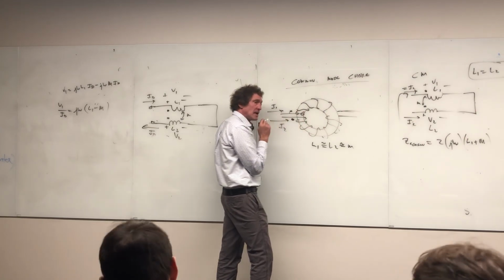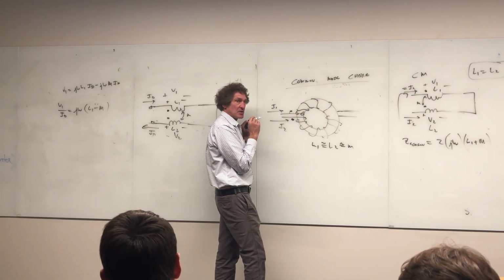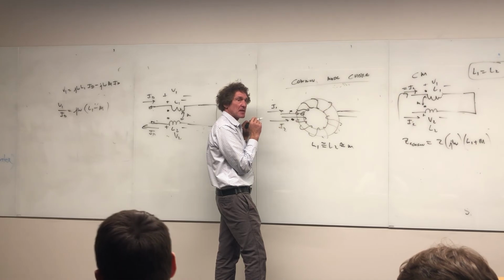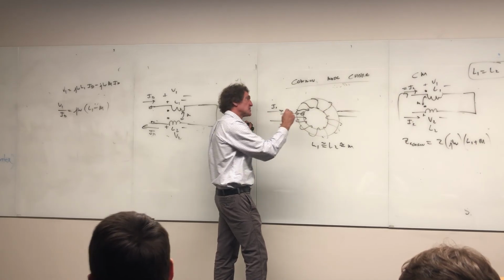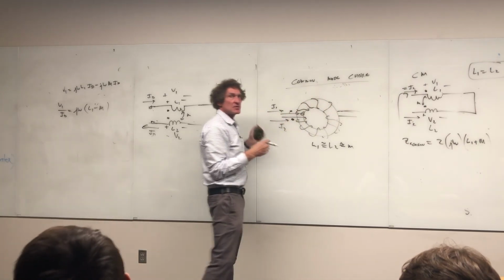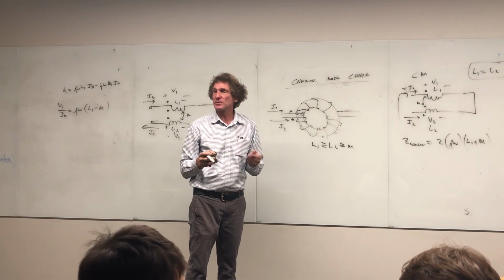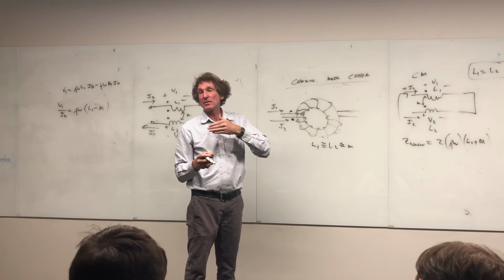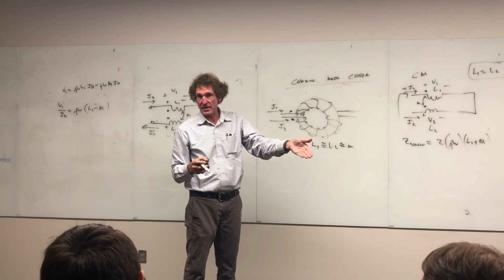This wire here is insulated, usually with insulation that can take maybe 1,000 volts, right? Maybe there's 30 turns, so it's 30 times 1,000, 30,000 volts more. Anything more than that will go right over that coil, it'll break it down.